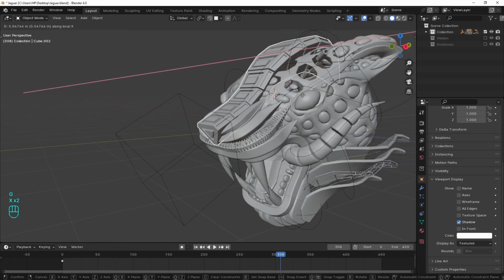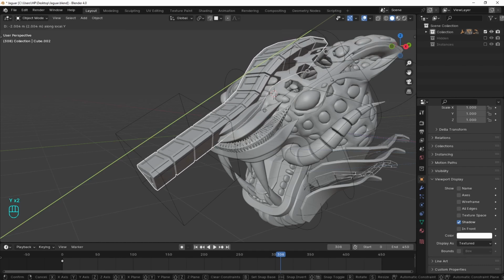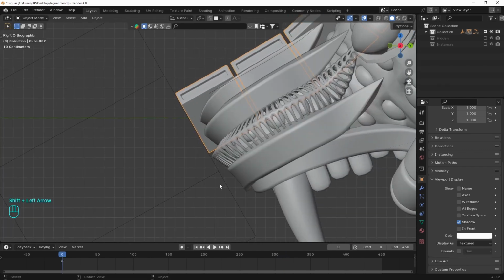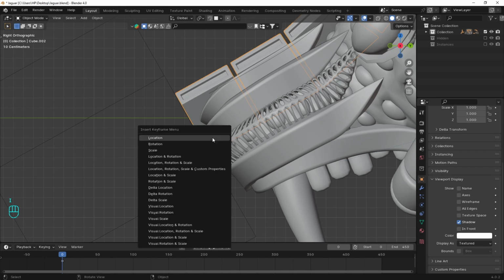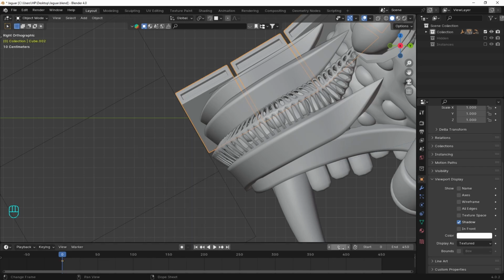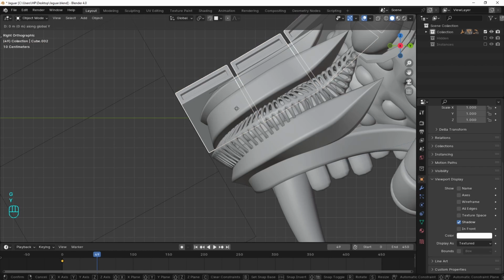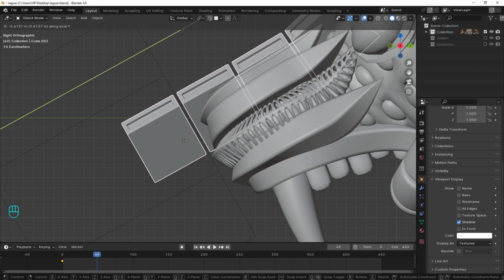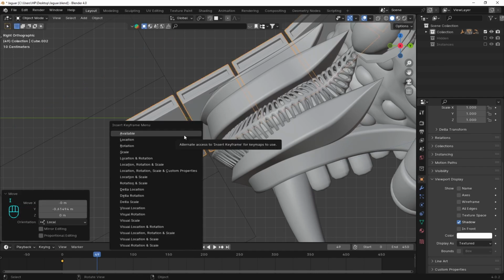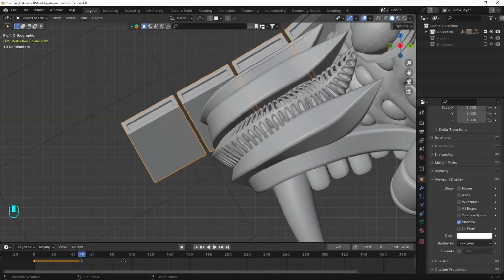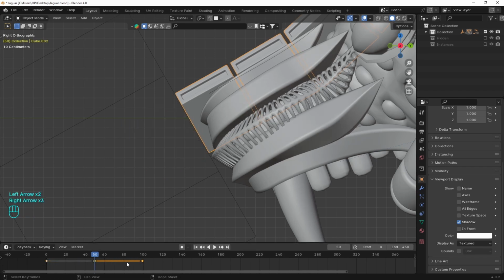Check which axis we have to animate, press it twice for the local axis, we are doing the Y. We will animate only one part of the array and put that on repeat, similar to what we did with the teeth but without the cycle modifier. So let's add a location keyframe at the beginning of the animation, offset the timeline with 50 frames, then move the array on the local Y axis, so the whole cube passes by the Boolean object. And now we just have to cycle this simple animation and it will look like the whole thing is moving. We have to do it in a way so when we duplicate, the first frame looks like the next step after the last frame, if that makes sense.